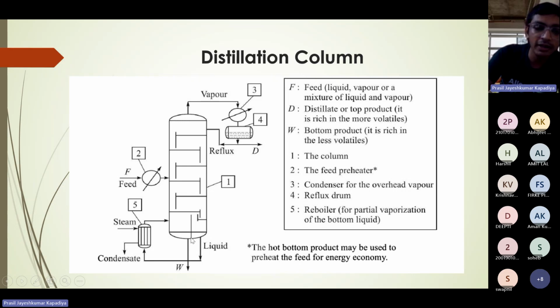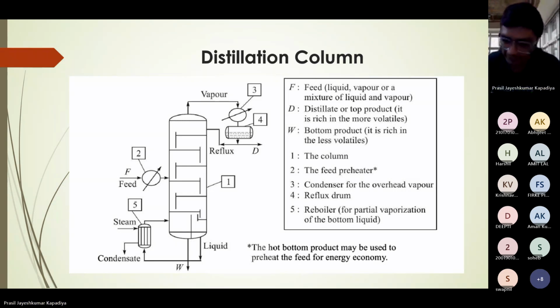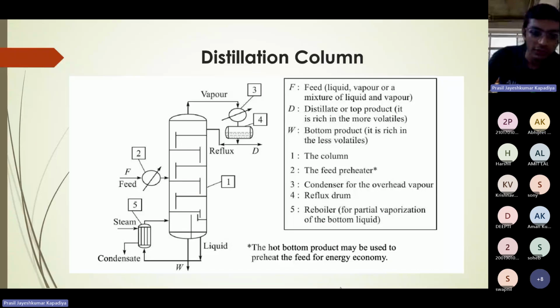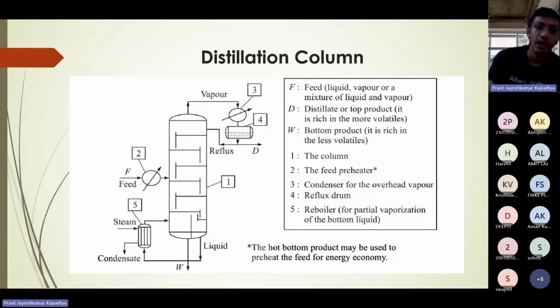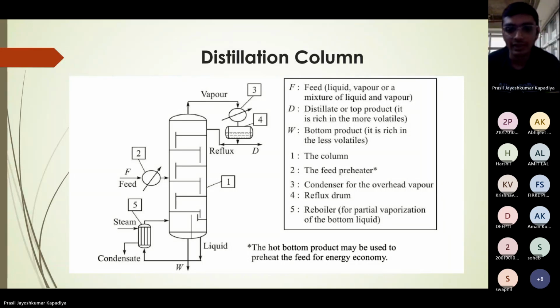Now let's say after this reboiler, the stream leaving here and the stream entering, which temperature should be higher? The temperature leaving the reboiler stream or the temperature entering the reboiler stream, which one should be higher? Leaving the reboiler stream. Okay, which temperature will be higher, at top or at bottom? Bottom is higher. Okay, bottom.